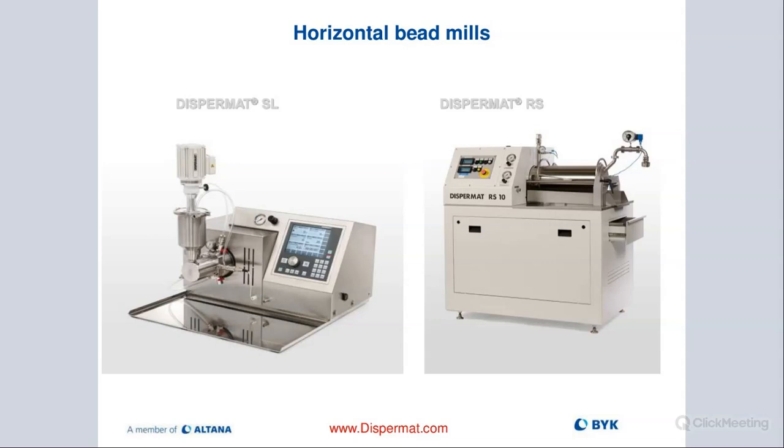And you can also do pass through. So if you want to just go one cycle, you're done, or move it to another mill. Some people set up numerous horizontal mills in succession. So they go from one mill to another mill to another mill. And the only thing that changes will be the screen size and the media size. So they basically go progressively smaller if they want to really have very fine material and they don't want to swap out the beads on one machine. So that is a way of getting down to very, very small particles very efficiently,